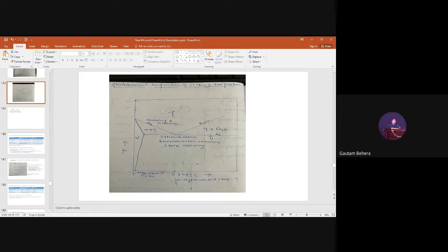Coarsening, or to spread along the grain boundaries? Network-like precipitation will not occur. Very good. We can have a precipitation, obviously, because it is a hypereutectoid steel, so the pro-eutectoid cementite phase will be there itself. You cannot avoid pro-eutectoid cementite unless you are going for non-equilibrium cooling, right? So cementite will be there and precipitate will be there, but it will not spread along the grain boundaries like in the earlier stage.